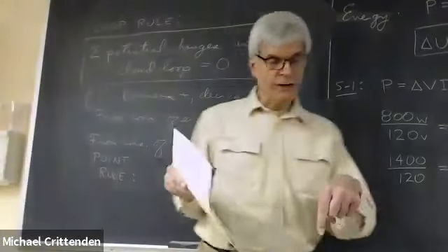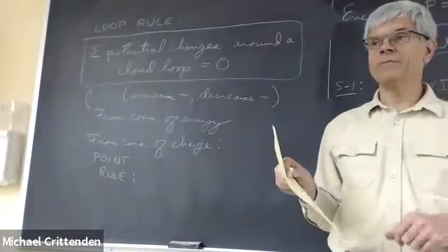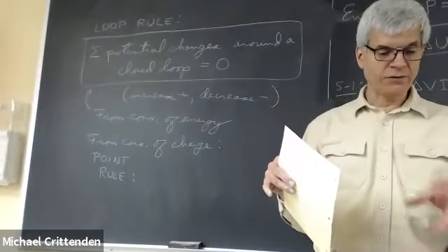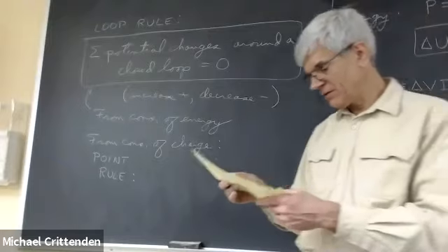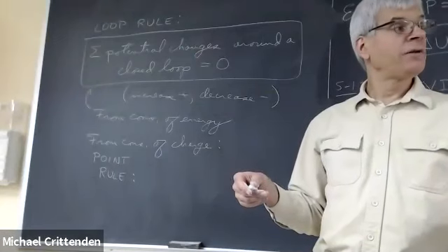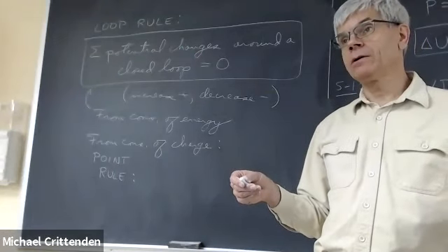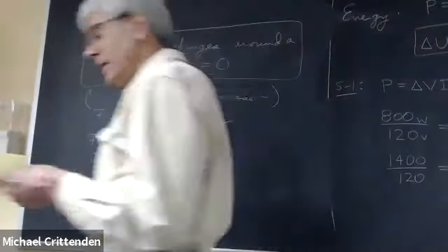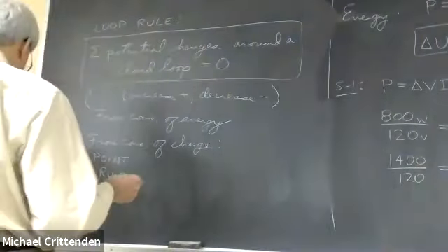You pick some point on your wiring diagram, typically a junction where some wires come together is a good place to look at. Total current flowing into that point has to equal the total current flowing out, because there isn't any way to store charge at a point, and it can't just disappear or something.